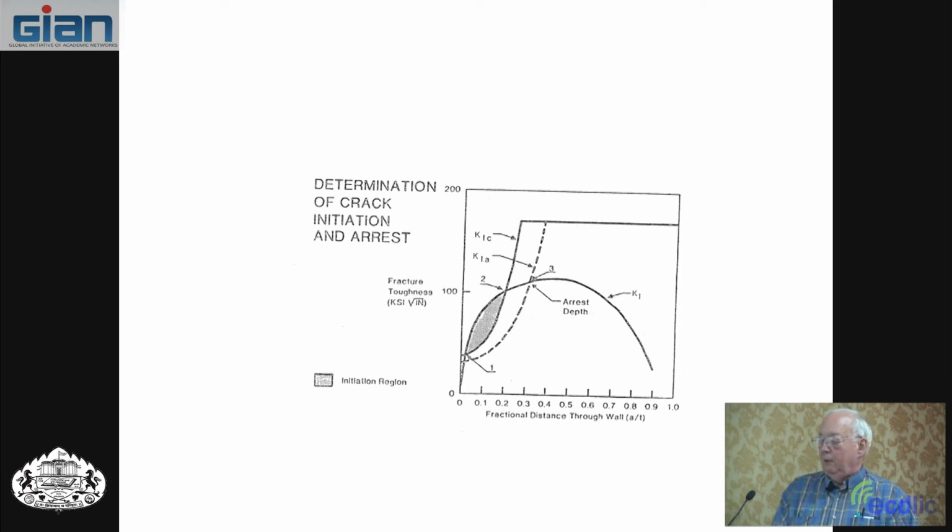Leaking, you know there's a failure about to happen, but leaking is not good when you have irradiated components and irradiation to leak out. So they want to have run arrest, finally in the end, complete arrest, and not through the wall. And so when they did this analysis, they found that, in fact, the analysis said it would arrest and not get through the wall, so it was safe. So this is worked out as being safe.